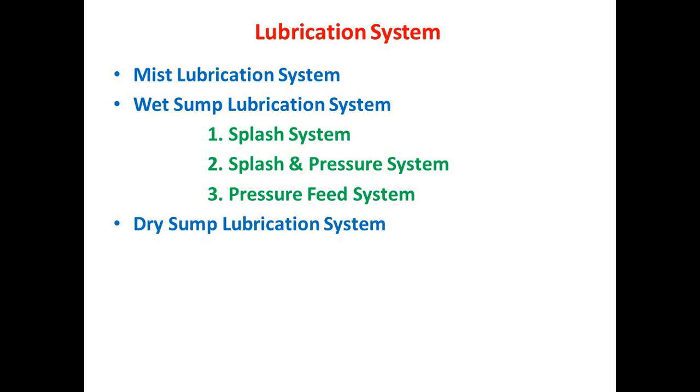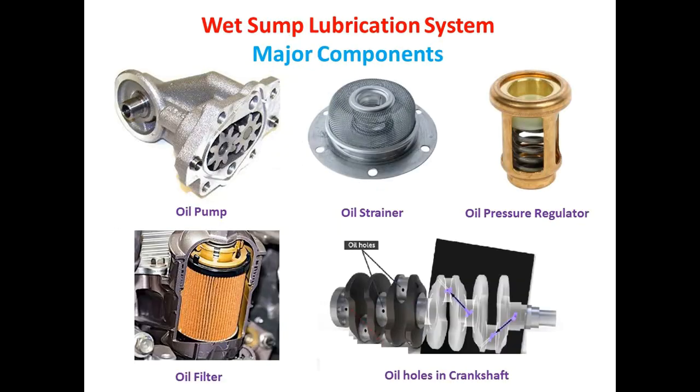Firstly, it causes heavy exhaust smoke due to burning of lubricating oil along with the fuel. Secondly, since it comes in close contact with acidic vapors produced during the combustion process, it gets contaminated and it results in the corrosion of the bearing surfaces.